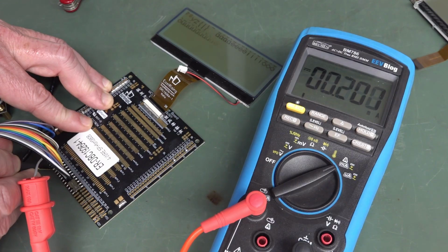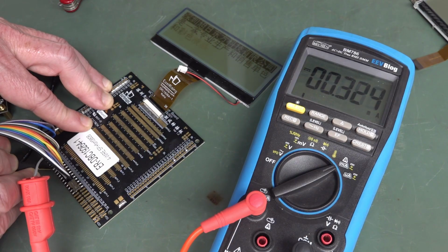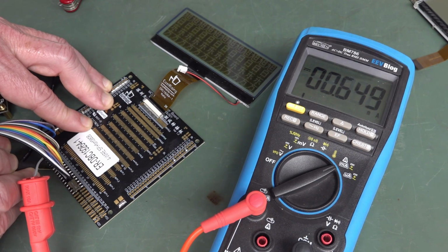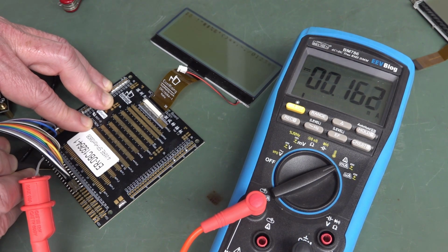Well, you can see it just reset. It dropped down to, what, 180? As it's put in more data on the screen, it's going to increase. And it'll increase as it puts more on there. But the datasheet value is 800 microamps, and it looks like 650. Okay, so yes, if all dots are on, then it could take 800.